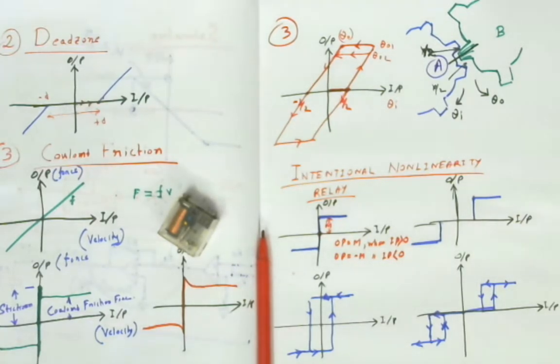For this reason, if you see the second figure, suppose I am applying 1 volt, 2 volt to the relay coil, that means you are applying input, and as I have made clear to you, the input axis in the characteristic curve denotes the relay coil current or voltage. So if you are applying 1 volt, 2 volt, 3 volt, you do not expect the relay to be on.